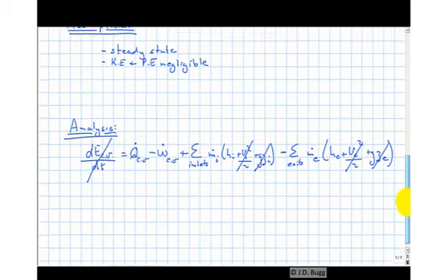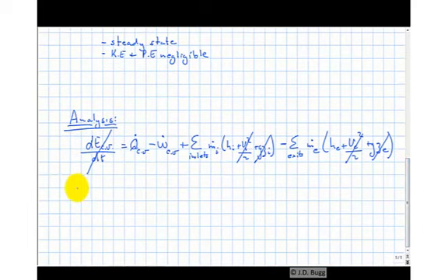this system at least. So we're going to start off by looking at the evaporator, because the first thing we want is the refrigeration effect, and that's Q dot in the evaporator. So when we apply this equation to the evaporator, we can make an additional assumption that there's no work transfer in the evaporator. Okay? So work is going to be equal to 0 for this particular component, as there's simply no shaft sticking out of the evaporator.